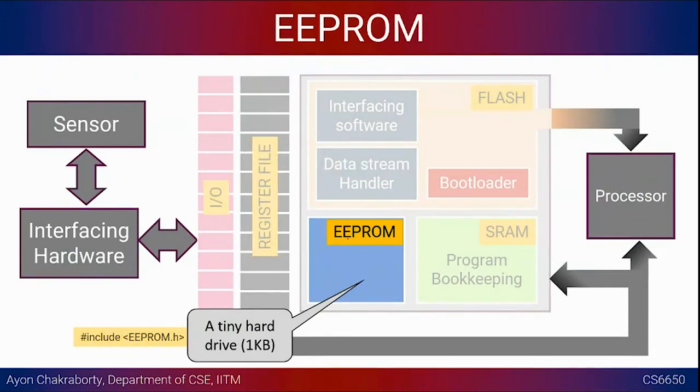Let's say you want to display some logo when your system starts, or there is a menu that you want to dynamically load, and you don't want to waste the application program space on all those menu items and some graphics. Those kinds of things you can actually put there. In case you have an LCD screen and you want to display something on the screen, in those cases, this would be very handy.